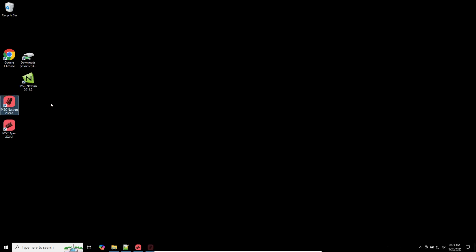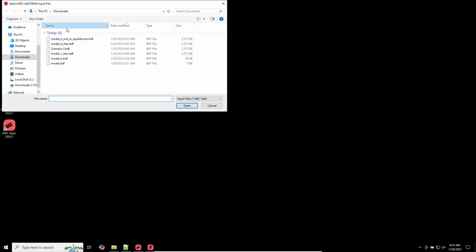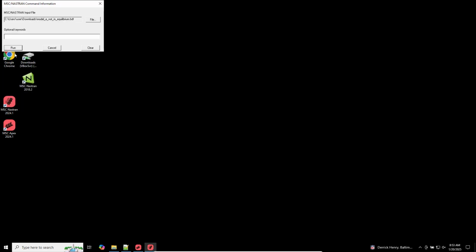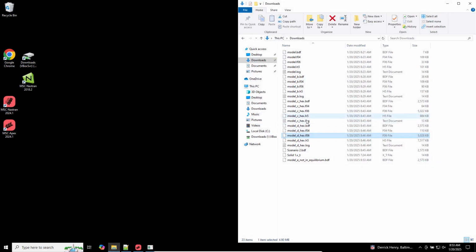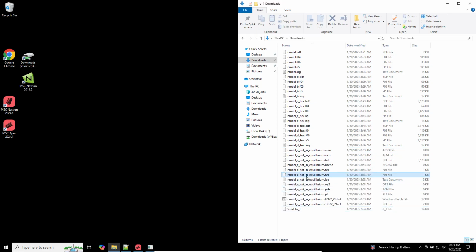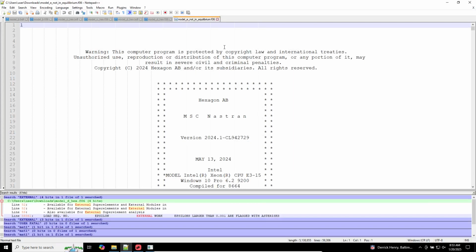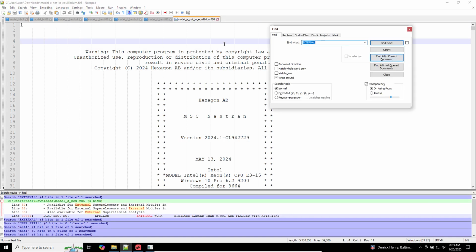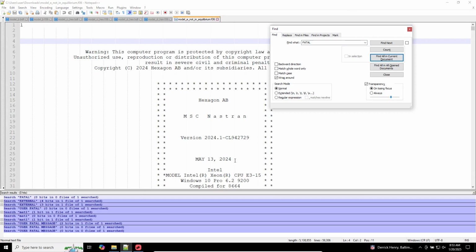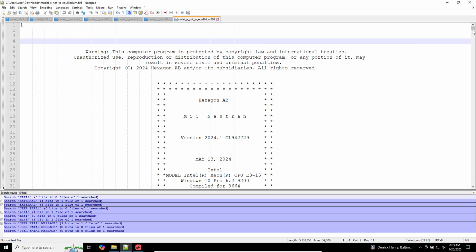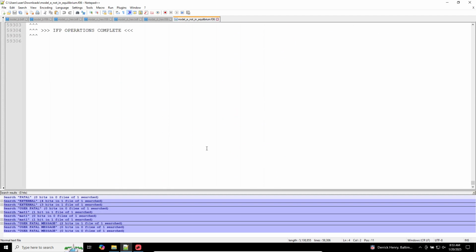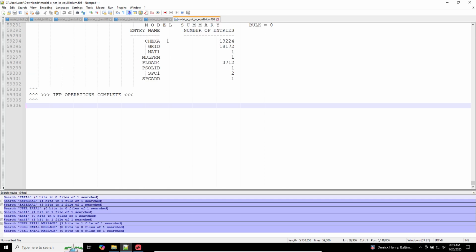Let's open Nastran and run model E. Now, we should expect it to fail because the model doesn't have enough constraints for equilibrium. When you open the F06 file, you're going to get the most common fatal message, user fatal message 9050, I think it's called, but I think it's been renamed in newer versions of Nastran.